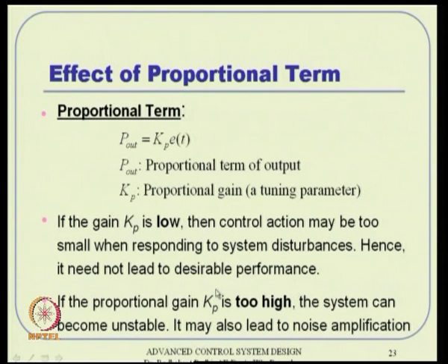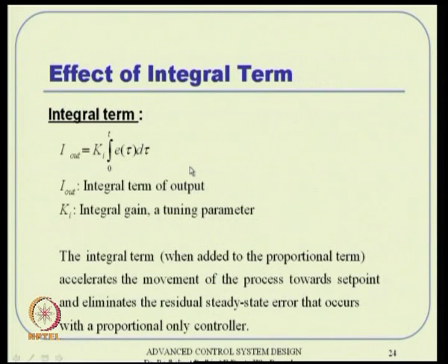And the moment Kp is very high, remember this all pass filter, all pass block sort of thing, any noise component will also get amplified by this value of Kp, and it will affect the system dynamics. So, that is also not desirable. So, just select this Kp judiciously.